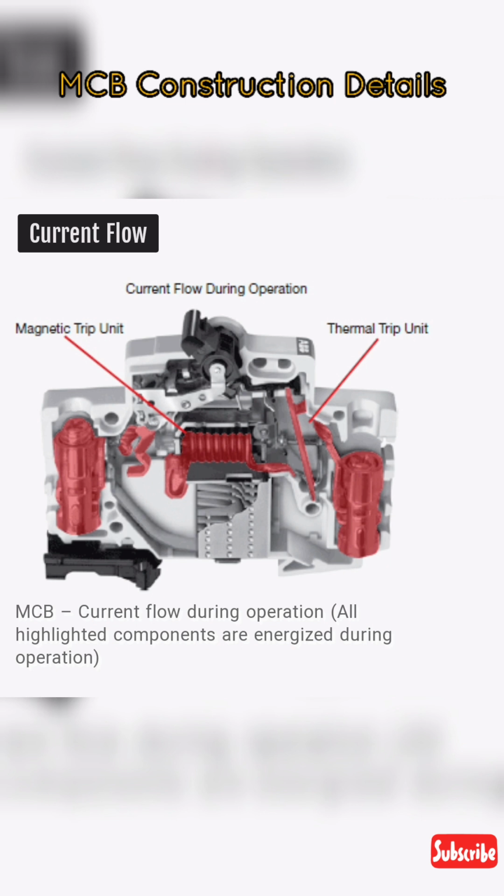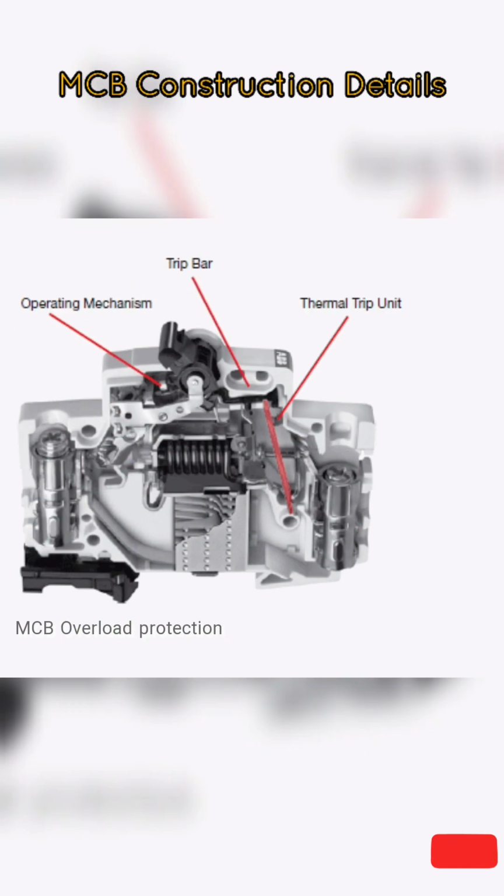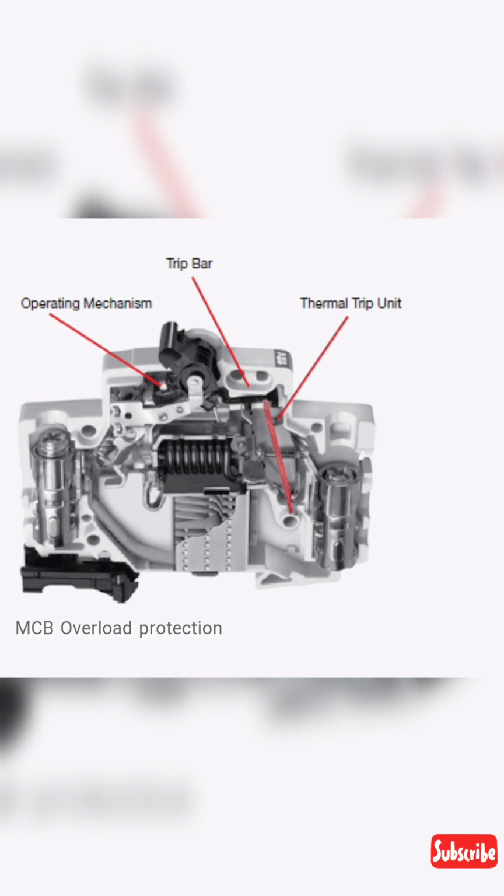The time required for the bimetal to bend and trip the breaker varies inversely with the current. Because of this, the tripping time becomes quicker as current increases in magnitude. Overload protection is applicable to any installation, conductor, or component which can be subjected to low magnitude but long-time overcurrents. Note: low magnitude, long-time overcurrents can be dangerous because they reduce the life of the electrical installation, conductor, and components, and if left unchecked could result in fire.